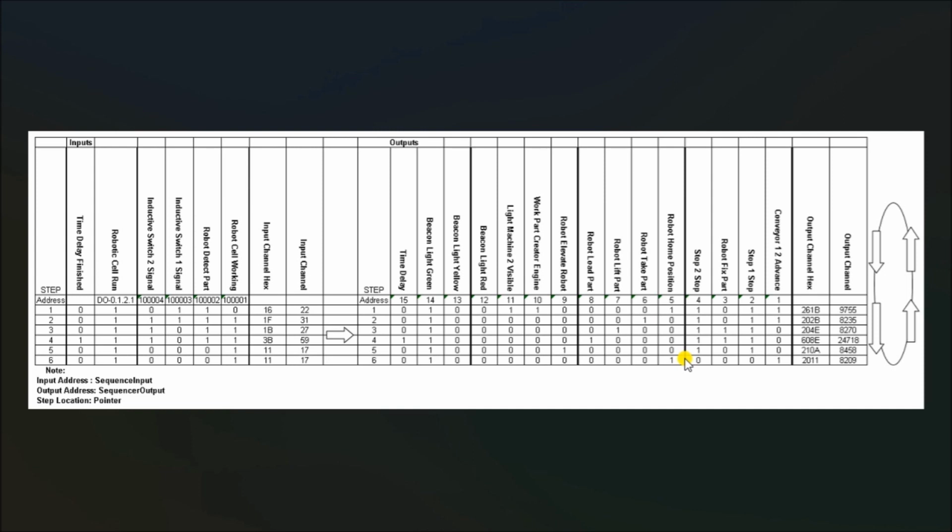Now keep in mind, step 3 is where we're actually going to be doing all of our main work and trying to develop what our sequence of operations is going to actually be. So you're going to spend a lot of time doing the logic and making all the errors here first. And it'll prompt a lot of questions. And those questions should be answered prior to you actually doing the programming, because the more questions get answered in this step, the less of the ladder logic that we have to actually program and continuously program to make up for errors. So as a programmer, you must fully understand all of what exactly has to happen within your sequence.